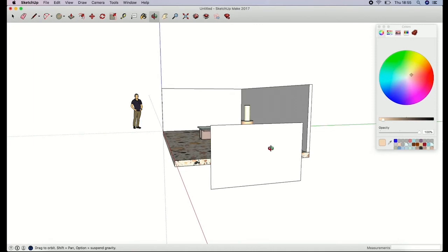So to make a chair shape, I could start with a rectangular profile. So have something like this. But also maybe it's interesting to have a curve on it. So with this tool here, you can create a 2-point arc or an arc between 2 points. I think I'm going to go arc between 2 points and start from here and go to there. Actually, go to the 2-point arc, sorry. So start from here and go to there, and then bring this out very slightly so there's a slight curve on it.